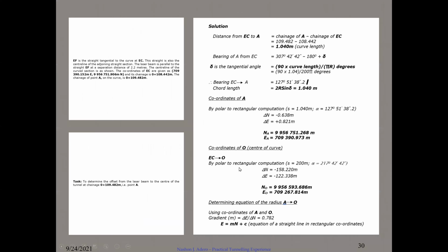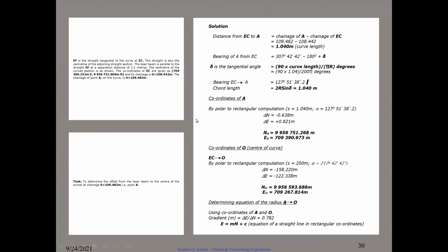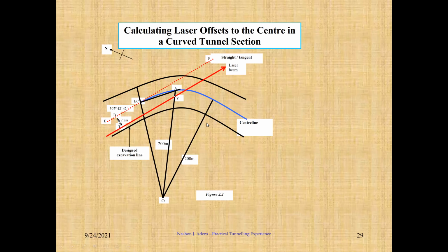So you see how long the calculation can be. So as a surveyor, you must do the calculation before you go to the tunnel. So you plan ahead of time. Before you go to the tunnel, you have your calculations right, so that you know at that chainage what you'll be giving the people as the offset so that work can proceed. So this is just an example of how long it can take to calculate that offset AY. It can take this long.